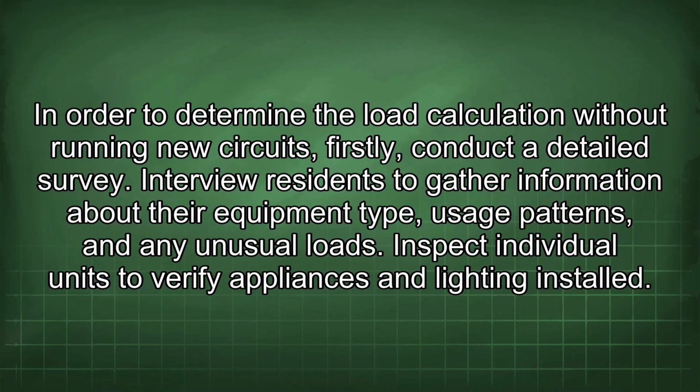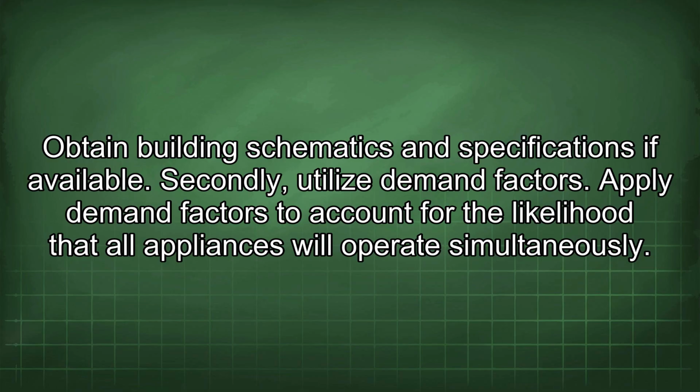In order to determine the load calculation without running new circuits, firstly, conduct a detailed survey. Interview residents to gather information about their equipment type, usage patterns, and any unusual loads. Inspect individual units to verify appliances and lighting installed. Obtain building schematics and specifications if available.